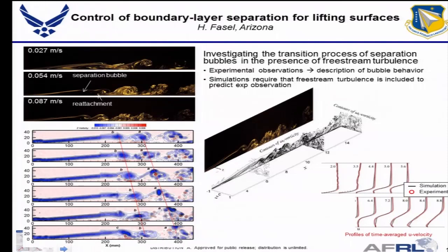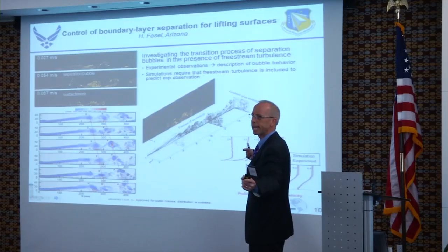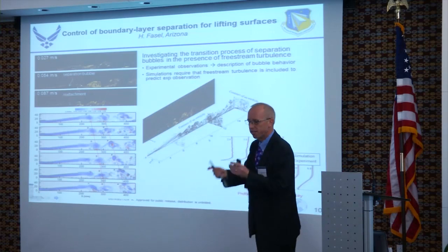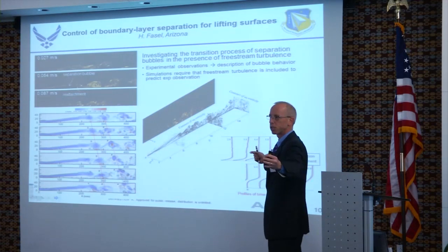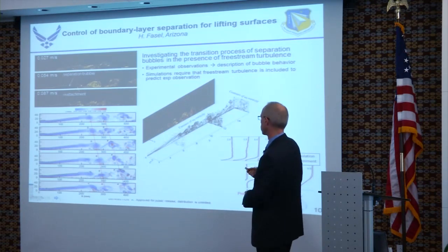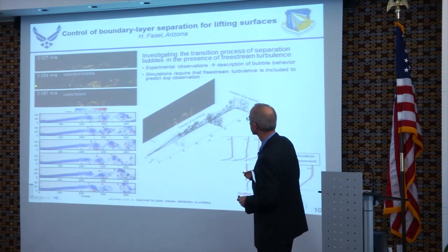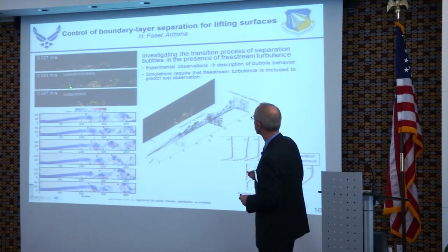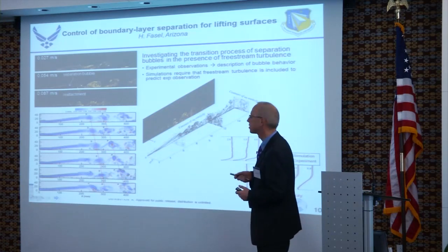It's at that sort of boundary that exists in the transitional part of the flow field. And so what we see over here on the upper left-hand corner, he's looking at this phenomenon across many decades of Reynolds numbers. So it's not just, oh, we're going to find out about it at a particular Reynolds number, but we're going to understand how transition occurs across all sorts of different scales of flow fields. So we see the formation of these separation bubbles. You can kind of see that in the flow vis a little bit if it was a bit darker, but basically the flow separates. It has an instability in it, it transitions, and then it reattaches.